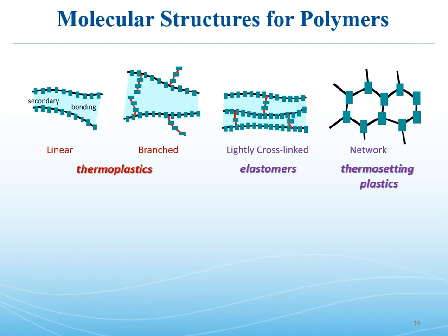So aside from thermoset and thermoplastic, which we can see here basically on the endpoints, we can get gradations in between. These are examples of macromolecular structure for polymers. So starting over on the left, you can have linear, just straight chains, and then those chains are attracted with secondary bonding. Very, very minimal van der Waals forces in the case of polyethylene, much stronger dipole-dipole bonds for polar molecules.